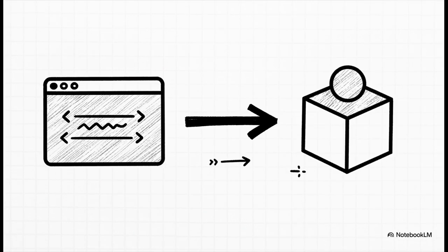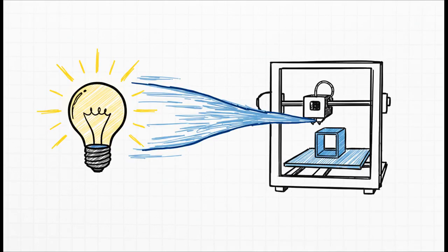Okay, now we're crossing back over to the world of code. This is OpenSCAD. It's the original, the classic. It's a simple, no-frills tool that does one thing, and does it very, very well. It turns simple scripts into 3D models. The beauty of OpenSCAD is really its simplicity. It's fantastic for whipping up a quick prototype, a simple bracket, a custom enclosure, when you just want to get an idea out of your head and onto the print bed fast.